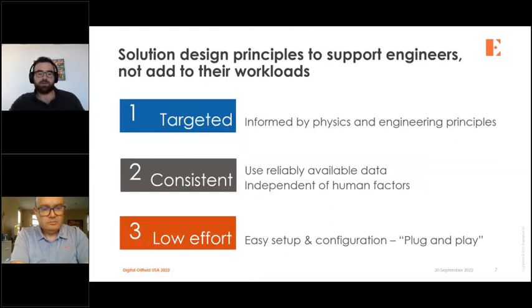So if you have difficulty rotating something, or difficulty lifting something, or restricted flow that comes from a packing off of the wellbore, then all of these things can be identified by looking at the right piece of data that streams off of the rig. So that's what we like to do. We like to think about the physics that actually relates to what being stuck means, or what the underlying sticking mechanisms are, and then we attack all of those directly in our solution design.